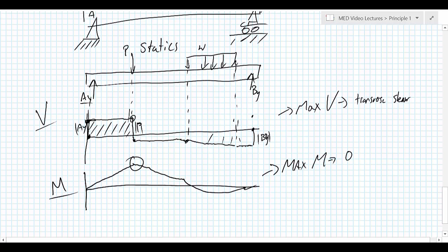And from that, determine our maximum normal stress as M y over I: the bending moment times the distance from the neutral axis divided by the moment of inertia. All right, so this tells us the stresses, which will be important from our last video when we talked about finding the principal stress values for a particular location. But what it doesn't tell us is how much this thing deflects.